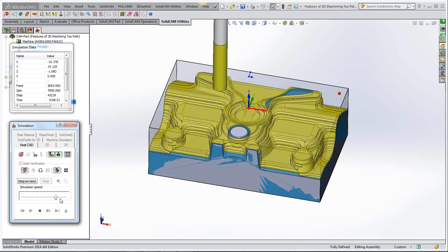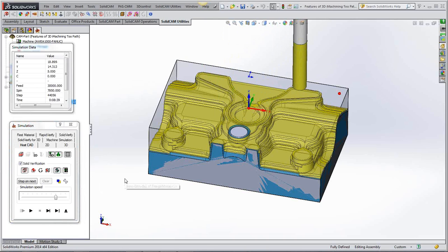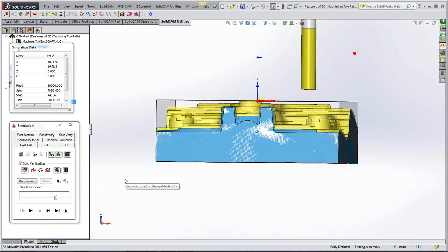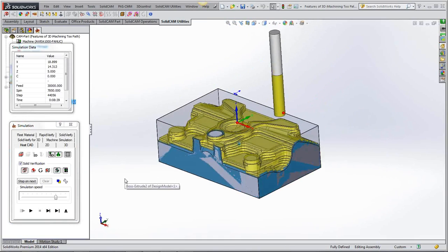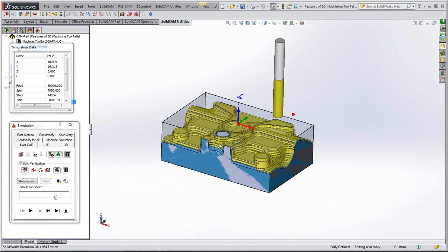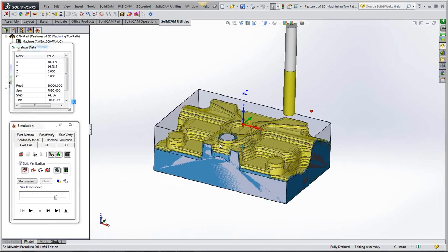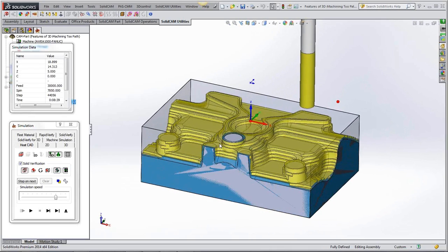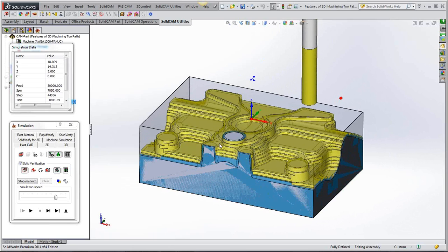And it's doing the top little bit of material as well, which you may not do in real life. You may have flicked that top or across there with a face mill before you've done this to get them levels. But either which way, iMachining is a very efficient way of removing that stock.